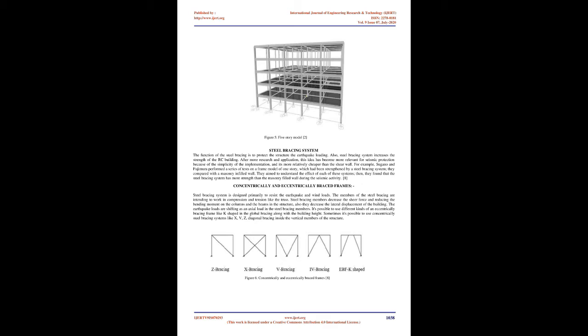Methodology. This part covers the modeling and base shear analysis of the structures. The most significant part is designing the RC models and checking their strength using SAP 2000 programming. SAP 2000 is utilized for the RC model during this study, and it is used for checking the quality and limits of the structural components before reaching the highest expected displacement of the model. The analysis method used during this study is the pushover method.